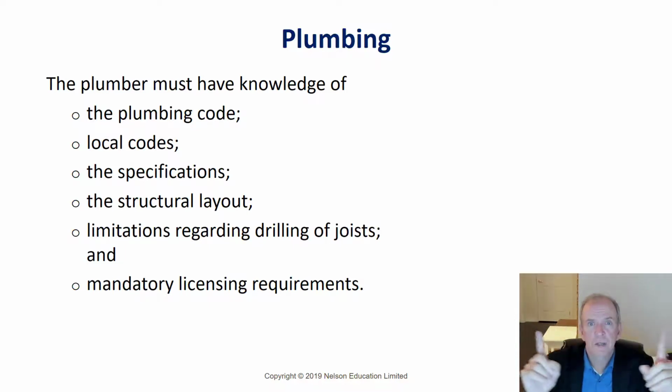Or you make it decorative, so you make like a coffered ceiling. If you look at the Brook drawings, I think the dining room has a coffered ceiling all the way around it. That would be a great opportunity to run some ducts and waste pipes if they're problematic in the rooms above. You can kind of make things hidden but look nice. That's a big deal with building systems. Nothing looks worse than just having a bulkhead and then it stops in the middle of a room. Like, what are you thinking? At least bring the bulkhead straight through so it looks clean.